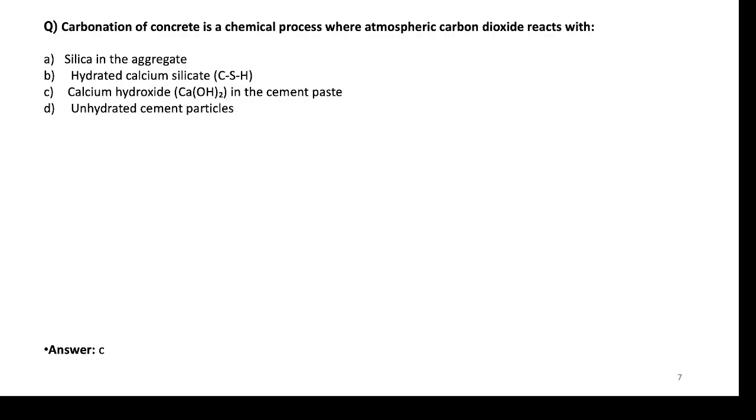So that is the secondary phenomenon that usually happens when there is a high replacement of mineral admixture added, which leads to reduction in the calcium hydroxide content in the pore solution. Because of that, CO2 directly attacks CSH structures. Hence, for now, for this question in general, option C is correct. We'll go with C. Okay, if you have any questions, you can ask now, or we'll see the next question. Okay, I think it's clear.